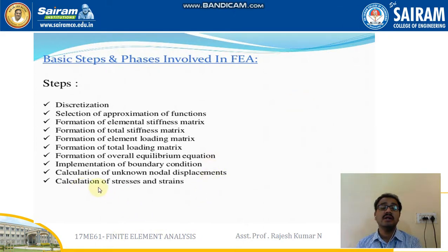The last step is calculation of stresses, strains and reactions. Stresses and strains can be calculated only for the elements, while displacements are calculated for the nodes, that is, the points where the elements are connected. These are the steps we usually use to find the solutions.